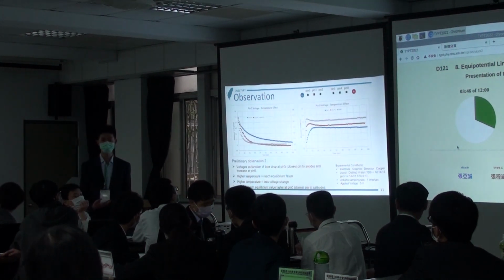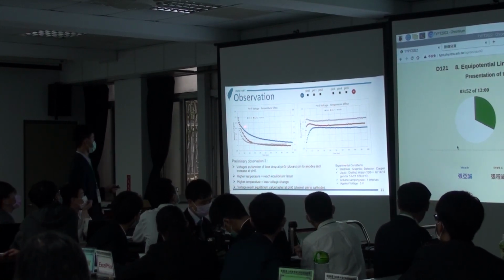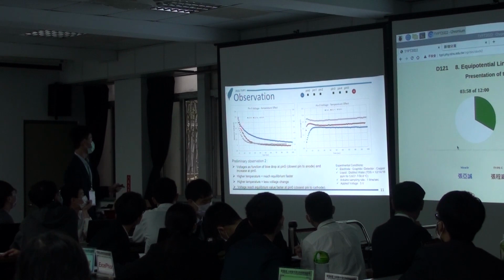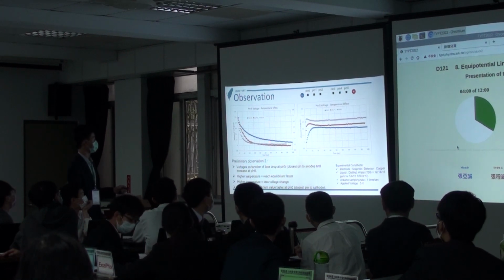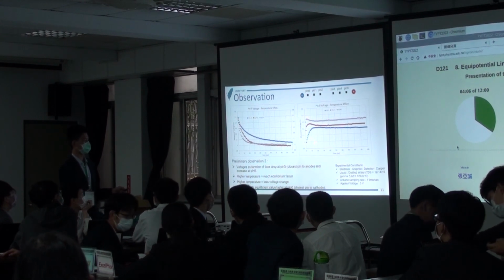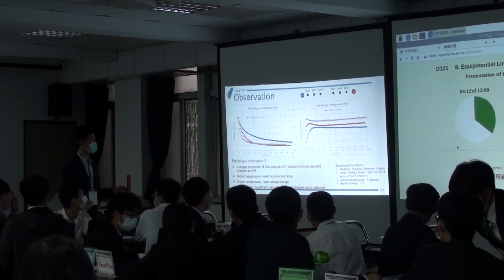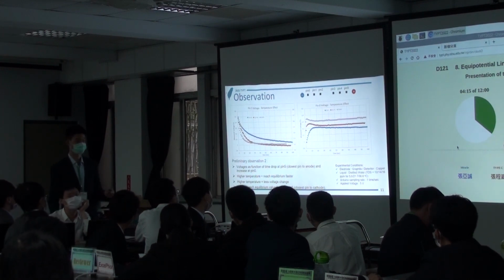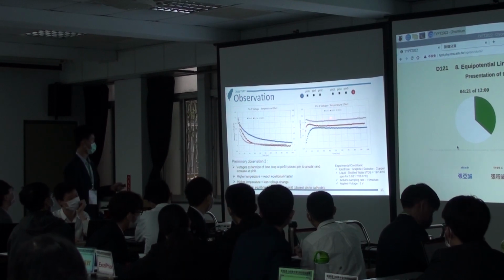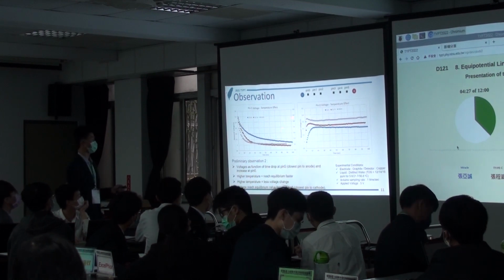To see what might cause this deviation in voltage, we have to observe how the equipotential line changes with time. This is the voltage we measured with experimental setup 2. This is the voltage change with time for pin 5. This is the voltage change with time for pin 0. Pin 0 is the closest pin to our reference, the cathode. You can see that voltage decreases for pin 5 and increases for pin 0 until it reaches equilibrium. Also, for higher temperatures, the voltage reaches equilibrium faster, and there's less voltage change. Finally, voltage reaches its equilibrium value faster at pin 0.